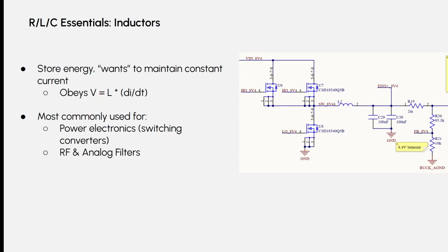So inductors are pretty straightforward. There's really not much to say. They're the same as the capacitors in principle: they store energy, but rather than wanting to maintain constant voltage, they want to maintain constant current, and they do this proportionally with their inductance value, their ability to store current. Most commonly used for power electronics. This is pretty much all we use them for. There are RF and analog applications of these guys.